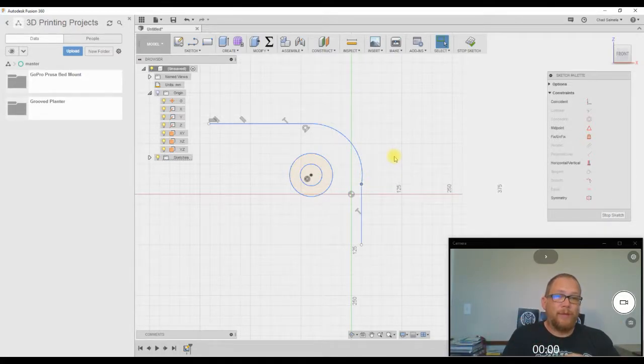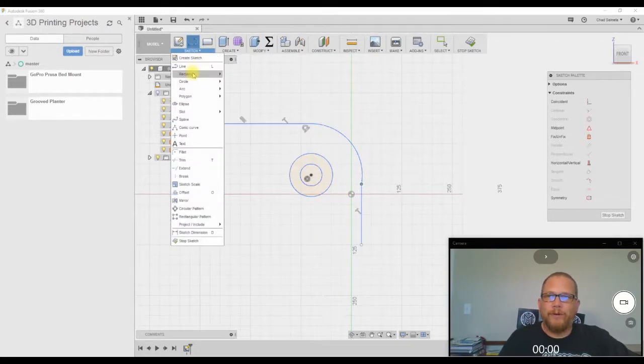There's not a whole lot to that one either, but again, when used properly, you can certainly eliminate dimensions, because you can do all kinds of stuff to get circles to be concentric. You could use the coincident constraint to put the center points of the circles together. That would work as well. But concentric's a nice way to do it, and it's nice because you get your symbols here that show you which constraint you've used.